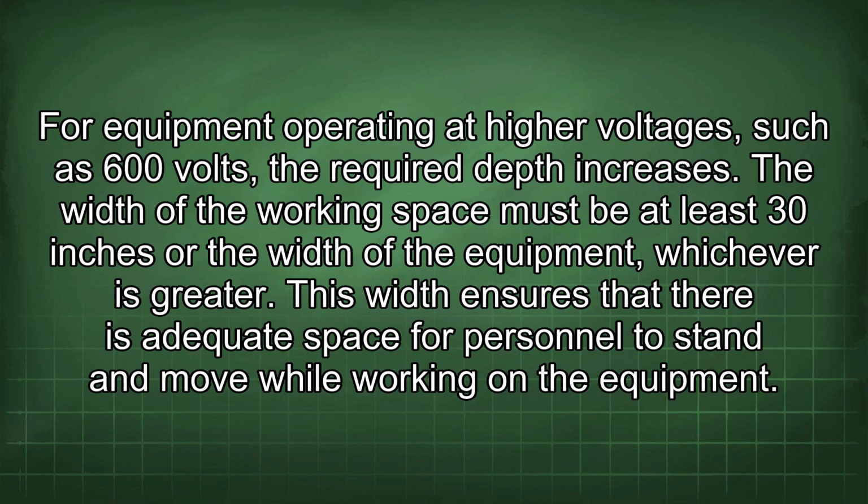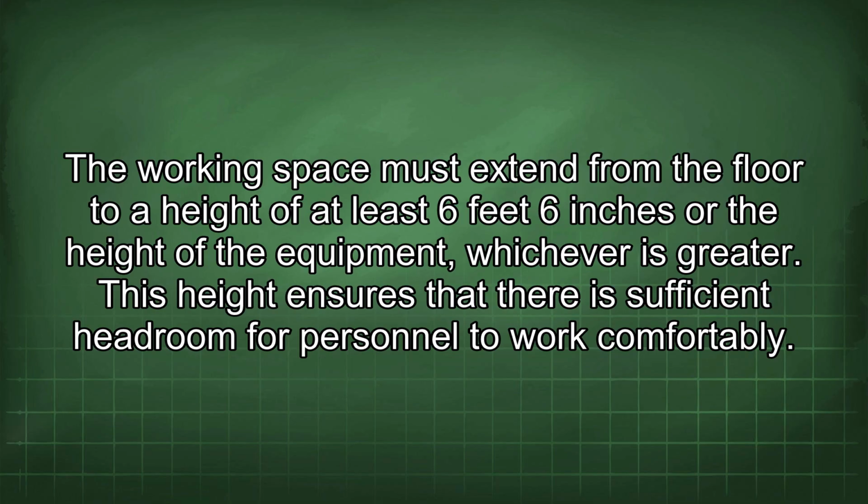The width of the working space must be at least 30 inches or the width of the equipment, whichever is greater. This width ensures that there is adequate space for personnel to stand and move while working on the equipment. The working space must extend from the floor to a height of at least 6 feet 6 inches or the height of the equipment, whichever is greater. This height ensures that there is sufficient headroom for personnel to work comfortably.